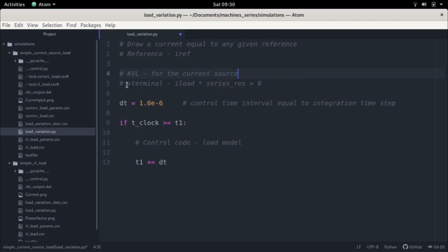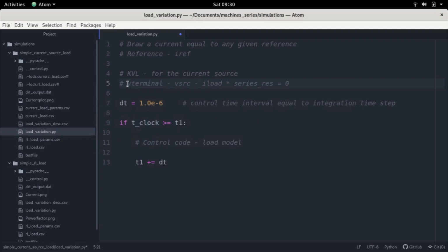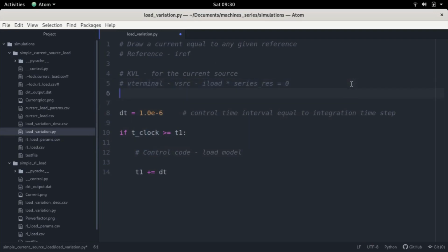Now, with this in mind, of course, I've forgotten the control source. How did I forget that? So anyway, what do I call this? I'll call this V source, right? So let's come back here. We are taking V measured minus V source minus I into this resistance is equal to 0. This is Kirchhoff's voltage law, right? We have this equation. Because we have this equation, we can now take this V source to the other side and just copy. I'll just copy this because I'm having trouble typing for some reason.